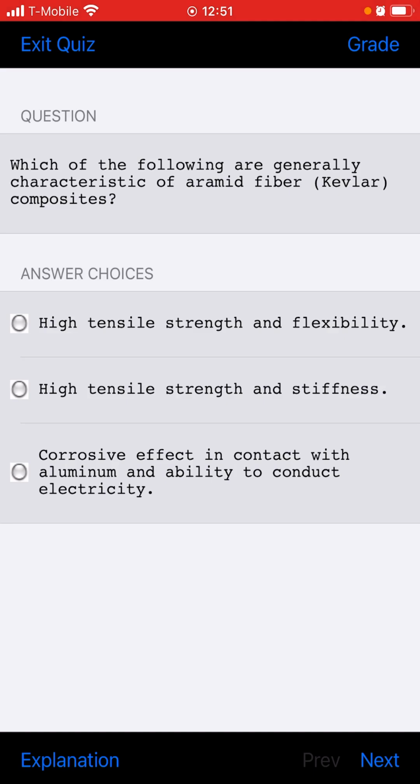A safety belt approved for installation in the aircraft may be identified by marking TSO C22 on the belt or by the military designation number for the belt. Military belts are approved for installation because their requirements meet or exceed those of TSO C22.